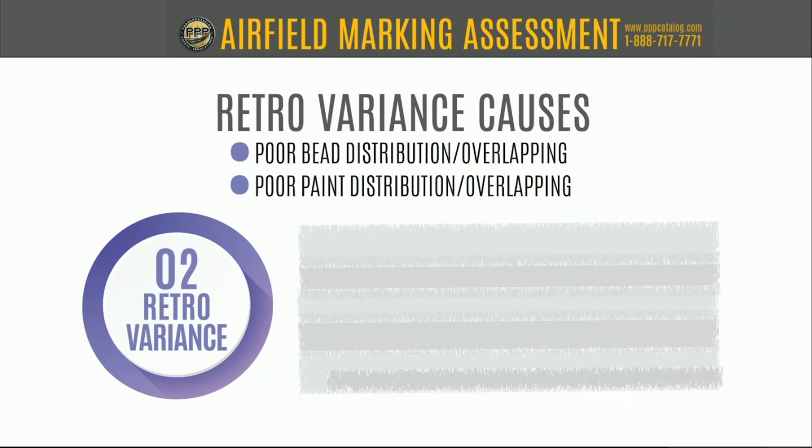Again, my ideal is, if it were my airport and I had to spec a truck to paint my runway markings, I want a truck with 6 paint guns and 6 bead dispensers, basically one for each 6-inch line. And so you are required to slightly overlap those paint guns. So essentially on a 6-gun setup, you have 5 individual overlaps in between each one of the guns.